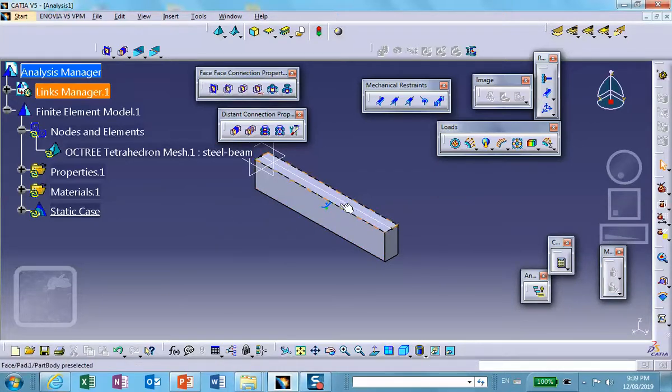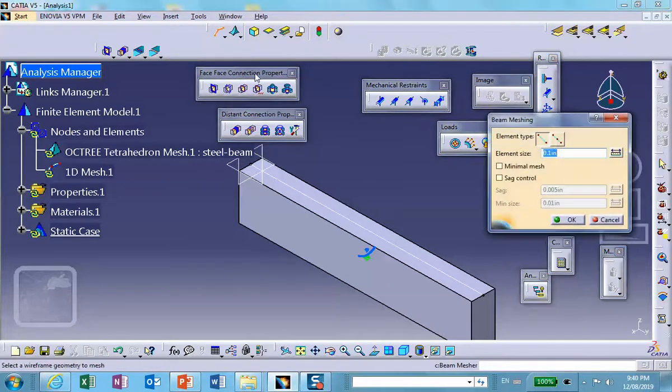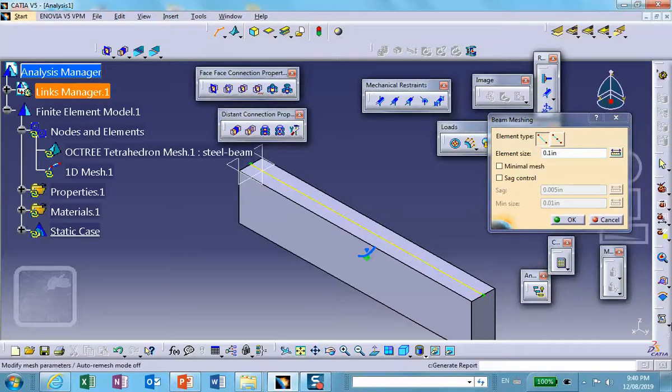All right, now let's mesh the beam, the line. Okay, so where is this beam elements? Right there. See that? Solid shell beam mesh. We select it because we joined it. Actually, it picks it, and this makes it 1 inch long element size. So let's make it consistent with the mesh on the solid. I'll make it also 0.2. It doesn't have to be. It's just that if you make it too big, you might have some problems later on with joining the two. Joining meaning creating connections between the two.